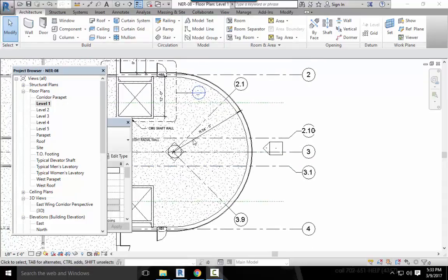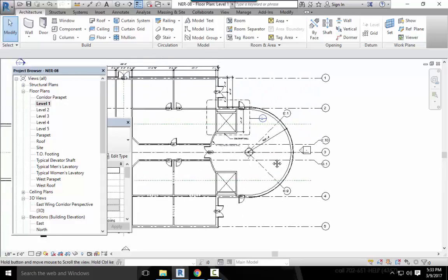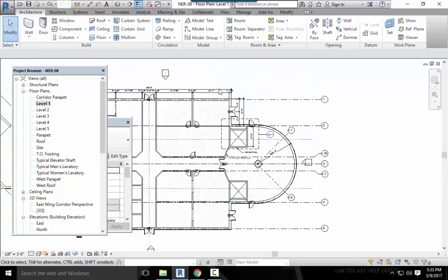Alright, the next step is to add the vertical grids. That will go this way, because really, structural elements tend to happen at the intersection of grids. The only real issue with adding vertical grids is the number versus lettering issue. Because Revit continues the sequencing from the horizontal grids, make sure that when you add your first grid going in the opposite direction, you renumber or rename the first occurrence of the grid.